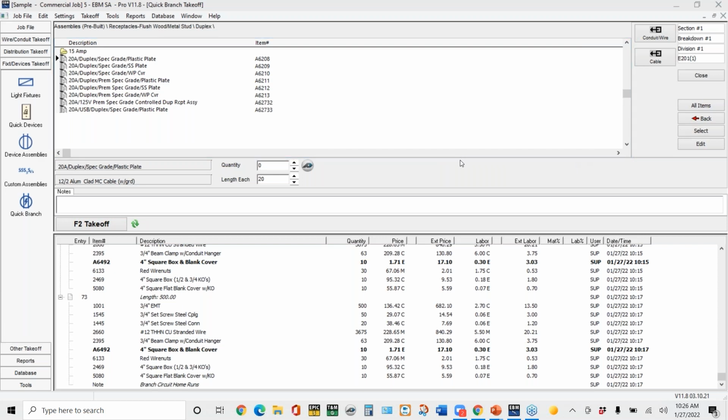Michael said, I do each of the outlets and lighting separately. Overall, it does typically come out to about 15 to 20 feet. Yeah, and I think that's not a bad idea. In my class, we do the whole calculation for the lighting, and then we do the whole thing for the branch power. But you could lump them all together. And again, it's probably going to come out in that 15 to 20 foot range.